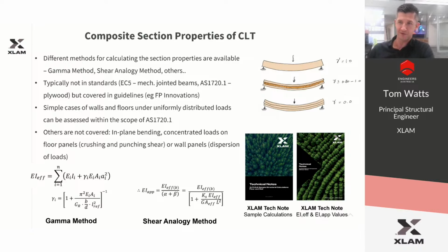So glulam beams are a pretty good example of a fully composite section, whereas CLT has the presence of the transverse boards. So that section of CLT is comparatively less stiff in a full composite section compared to glulam. But also keep in mind that it's still a fully glued section; the reduced stiffness comes from the reduced stiffness of the transverse layers. That's a fully adhesive connection. There's no slip in the connection. It's due to the material properties in that transverse direction.